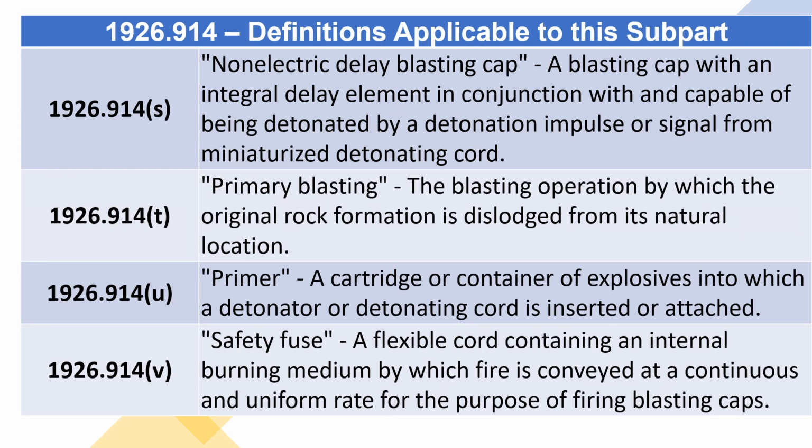1926.914(s). Non-electric delayed blasting cap. A blasting cap with an integral delay element in conjunction with and capable of being detonated by a detonation impulse or signal from miniaturized detonating cord. 1926.914(t). Primary blasting. The blasting operation by which the original rock formation is dislodged from its natural location. 1926.914(u). Primer. A cartridge or container of explosives into which a detonator or detonating cord is inserted or attached.